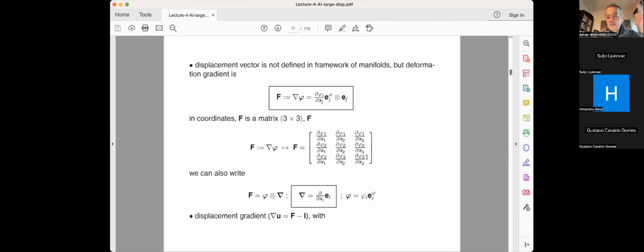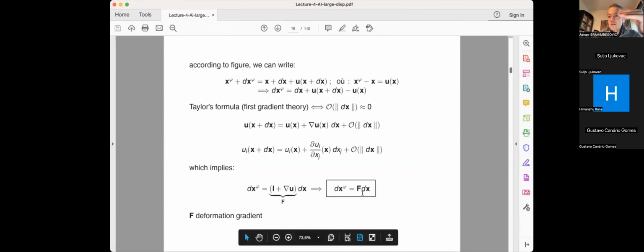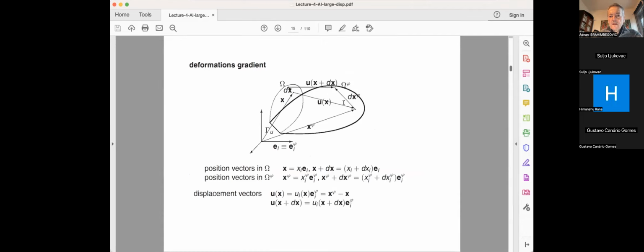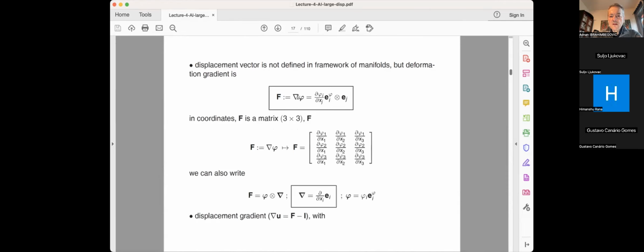We're going to be using as the first strain measure this deformation gradient, and this strain measure tells you how the infinitesimal vector of length dx will be changing to the length dx phi. So you can see it on this picture. dx phi is at least 3-4 times bigger than dx. So obviously it changed a lot. You have a large deformation to get such a configuration.